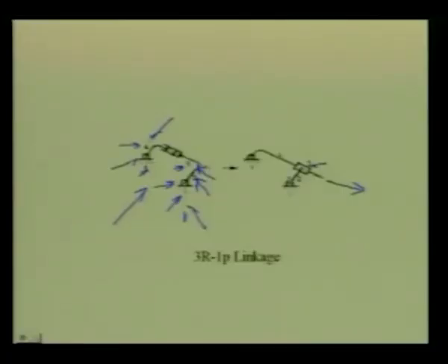So it has 2 kinematic dimensions, namely the length of this link, let me call it L2, and the distance between these 2 revolute pairs located on link number 1, which we may call L1. So L1 and L2 are the only 2 relevant geometric dimensions, and the direction of this prismatic pair, which is parallel to this direction, is important, and that has been written. This is what we call a kinematic dimension of the original mechanism.